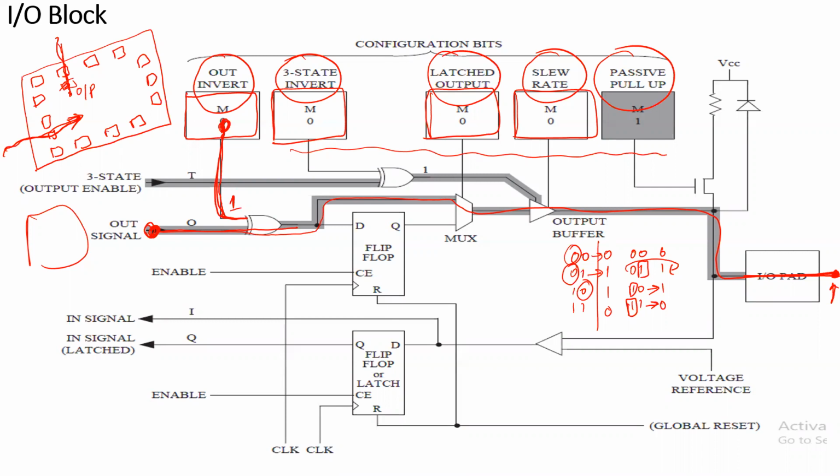So that means we have to program this configurable memory block to assign logic 1. Here is logic 1 we have to assign, so that whatever output we have here will be complemented at the output side. Clear? So like this, if we want to have a tri-stated buffer, we have to disable these particular components.